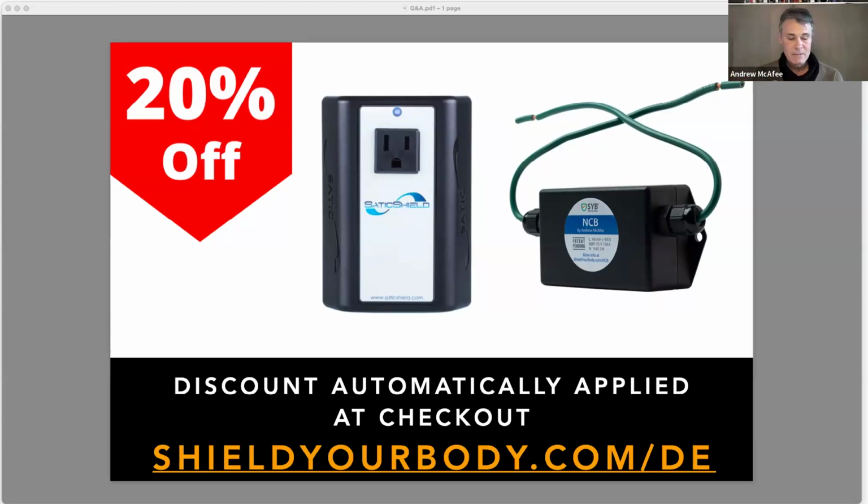Now, all of this has to be done correctly. You have to have an electrician. You have to have the diagnostics done correctly. You never, ever want to cut multi-wire circuits, shared neutrals, all this other kind of stuff. It gets more complex, but you have to understand the layers that we're talking about.